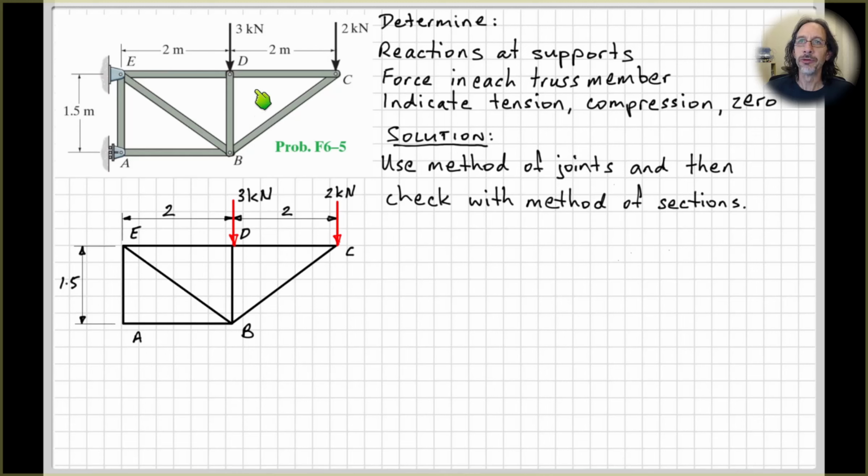So, if we really did have to analyze and design this truss, we would of course need to know the reactions at the supports, right, as well as the forces in all of the members and joints, not just one or two of them that may have been asked for in the question. Okay, and it's also good exercise to go back and revise your rigid body equilibrium. And it also, as we'll see at the end, provides a good check of our method of joints and or sections that we've used. All right, so there's my free body diagram,